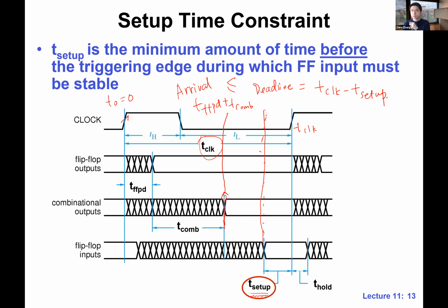All right, so there are more questions. What about the unstable bit between deadline and arrival? Oh, so you're asking about this one, right? This crosses basically means that we are propagating the signal. So basically the D2, right? This signal is not stable yet. That's why I'm using this crosses. Is it clear? Right. So basically they're not stable yet. It takes time for the output to be stable.